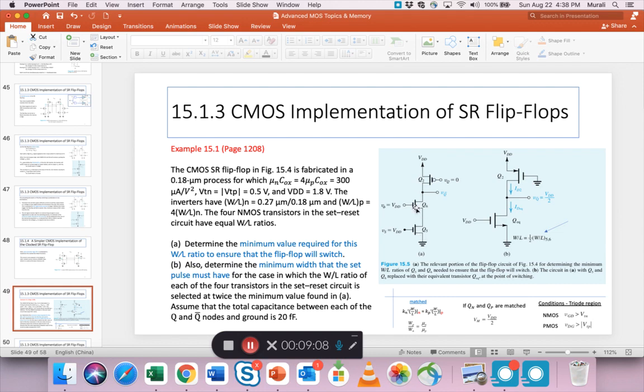So this is a bit like connecting capacitances in series. When you connect capacitances in series, the total capacitance is half, right? Similar to that, the W by L of the series combination becomes half. So he replaces these two with that, and then he's still got Q2.